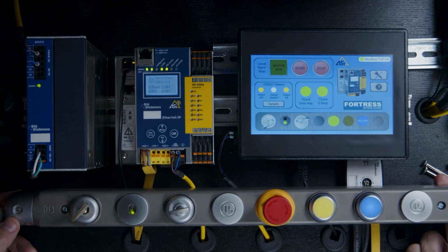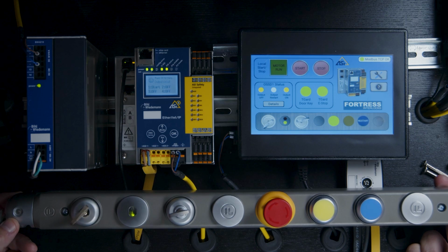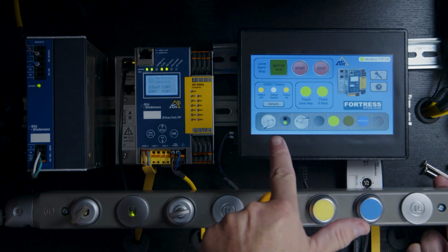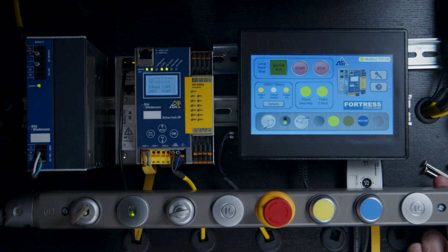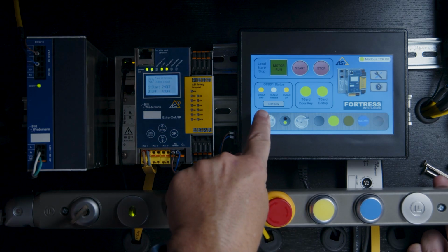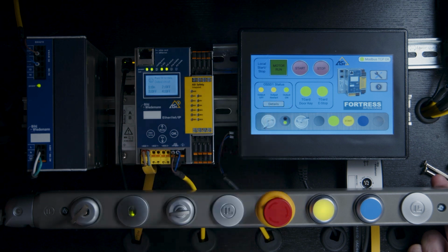All right, let's take a look at the final demo we have here on the bench now that everything is configured and I've got a program running in the OCS controller. So what we're doing here in our demonstration is we're mimicking what we've got going on with our tGard, with our blue and yellow lighted push buttons, our e-stop button, and our two key switches. Currently our safety circuit is waiting to be restarted. Once again, we're using the blue push button to restart the safety circuit. Once that's pressed, then everything is good here.